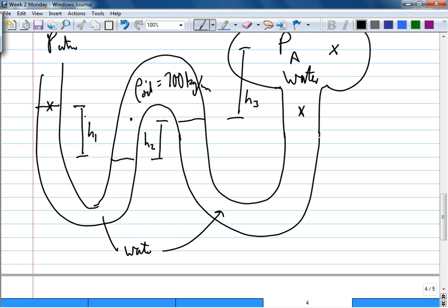So we start from where the fluid is connected. You start here. At this height, the pressure is the same. Let's call it point 1. On the left hand side, this one needs to go down and then up again. Is the pressure the same here? That's 2. And that one, here and here, is the pressure the same or not? Because here it is continuous liquid, stationary, all these things. So yes, P1.